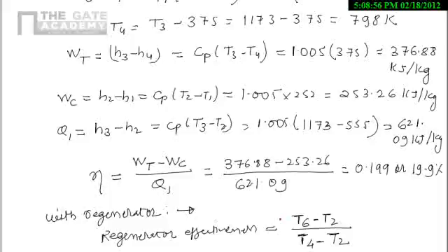In the maximum temperature gain condition, the exit temperature of the turbine and the entering temperature at the combustion chamber should be the same. Means for maximum temperature gain, the temperature at the exit of the turbine, that is T4, and the temperature at the entering of the combustion chamber, that is T6, so in place of T6 I can put T4 for the maximum condition.